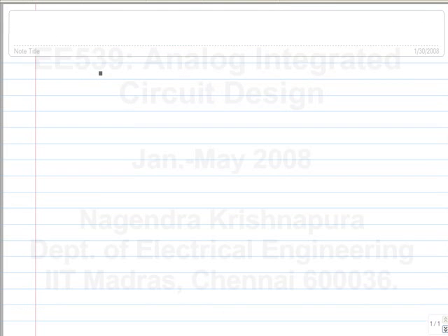So far we have been discussing the DC small signal model of the MOS transistor. Now we can move on to the AC small signal model. It's an addition to the DC model in that we also include the charge storage effects, basically all the capacitances that come into the picture. The AC model could also have inductors, but at the frequencies that we are interested in, there are no inductors of significance.